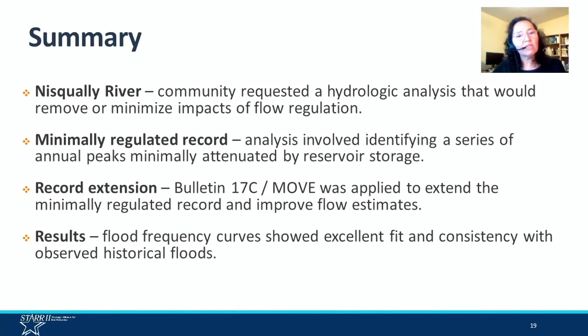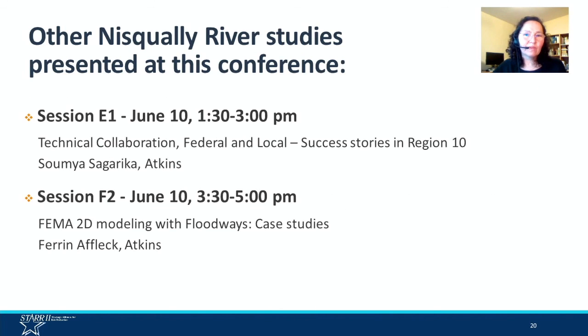Given that the minimally regulated record was much shorter than the regulated record, we used record extension following Bulletin 17C to reduce associated uncertainty. Finally, our results showed excellent fit and were consistent with historical floods.